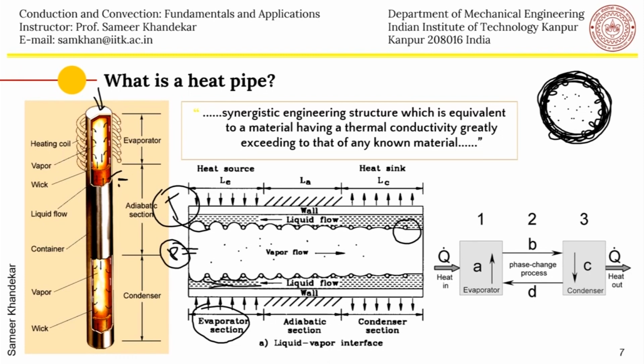And if you will recall, the Young-Laplace equation and the Clausius-Clapeyron equation have to work together for this system to start working. So of course there will be a Young-Laplace pressure difference because you have an evaporator section here and the pressure is increasing, and therefore the local pressure in this region will increase, and this pressure of the vapor is higher than the pressure in the liquid. And therefore across the interface there will be a depression of the interface, and the curvature will be determined by the Young-Laplace condition.